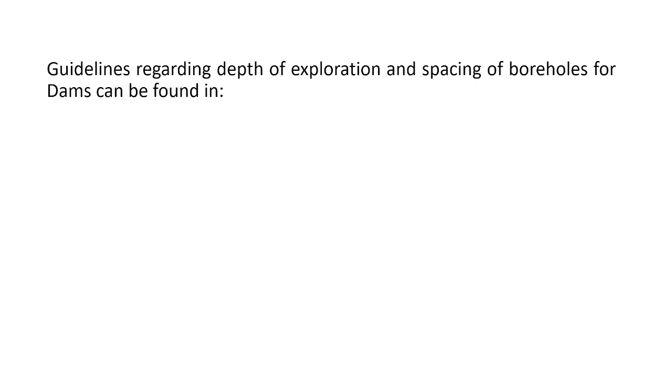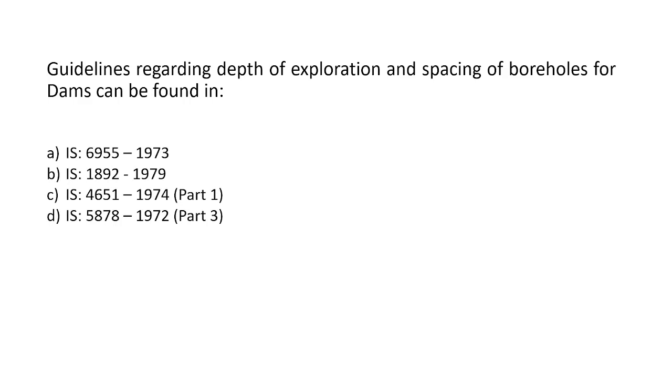Okay. Next, we'll move on. The question is, guidelines regarding the depth of exploration and spacing of boreholes for dams can be found in which code? So the answer for this will be, see, IS code. When you use it, you refer to it several times, you will learn it. Okay, so the guidelines for the depth of exploration and the spacing of boreholes for dams is given in which IS code? Yeah, correct. So it will be in IS 1892 1979. Sorry, okay, for dams it is, right. So for dams it will be in IS 6955 1973.